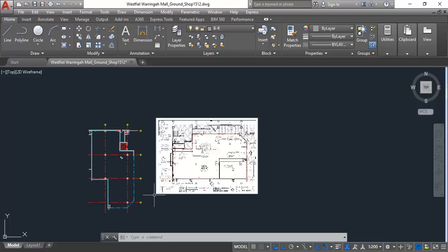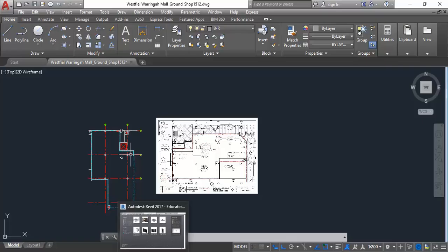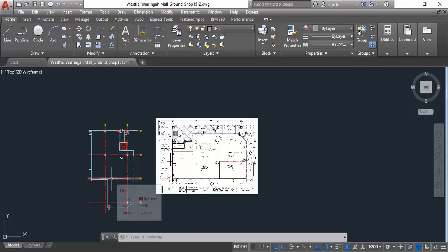Not so much your overall layout, but you at least want to settle on the orientation you're going to use for your main drawings, particularly your floor plans, because that can be difficult to change midstream if you need to rotate all of your plans differently. It's technically quite a difficult thing, particularly in Revit. You can do it, but it's much easier if you get that right at the beginning and stick with it. So I actually think it would be better to rotate the AutoCAD plan personally